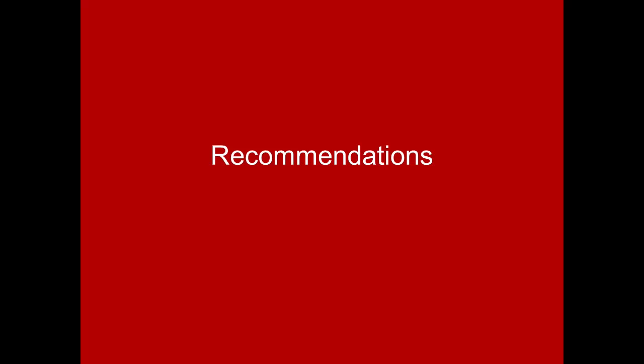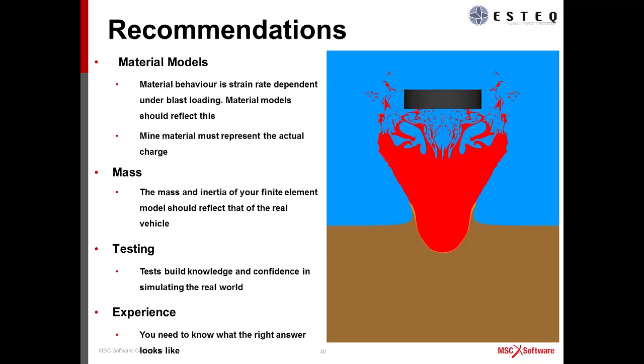Okay, and then finally, I'd just like to draw your attention to a couple of important points that you should consider if you are going to perform mine blast analysis. The first is material models. Material behavior under blast loading is typically strain rate sensitive, so your material models should reflect this.